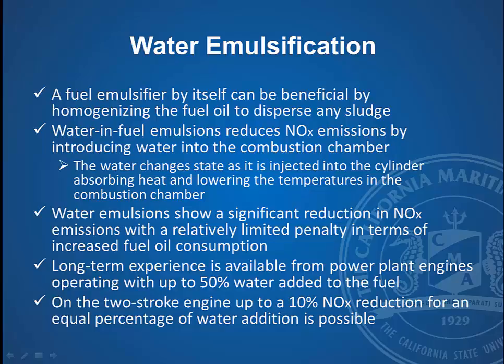Another subject as far as lowering NOx, and this is one way of removing NOx that is currently being used. A fuel emulsifier by itself can be beneficial by homogenizing the fuel oil to disperse any sludge. This has been used for quite a few years, as in you're putting the fuel through an ultrasonic, and any small amounts of water and sludge bond to the fuel molecules, and it is said to give you better combustion.